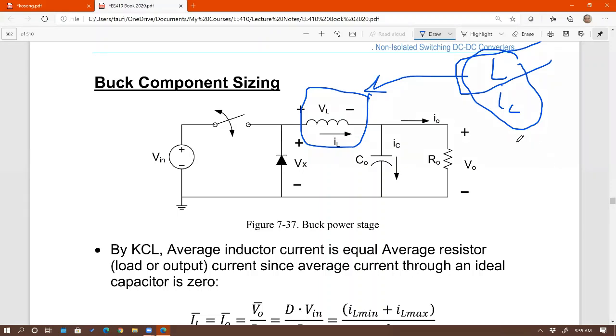No, we're not talking about transient, steady state. The wire is going to get too hot. Most likely, in a DC to DC converter such as this one, it's going to damage either the switch or the diode first before it can damage the inductor.